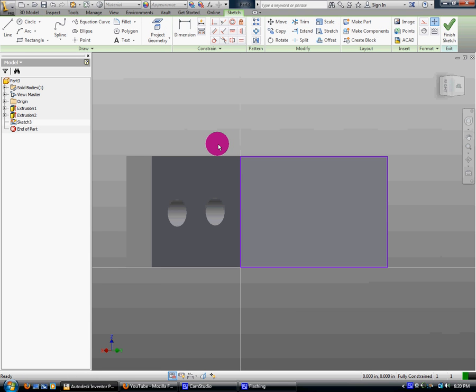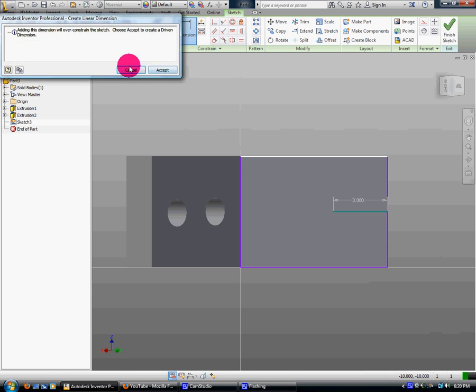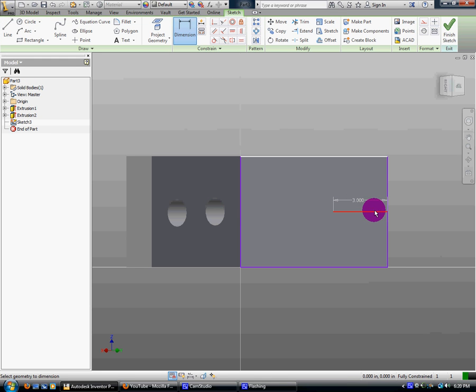And this time, I want to find my center hole, if I remember correctly. Yep. So it's going to be 3, 3, and 2. So I'm going to draw a line from the center here and over, and measure it. It needs to be 3, and if it's been done correctly, from here, cancel. That'll be 3, okay? And it is good. You could also just simply put a point there, and you could draw off that, but just drawing it for now. Okay, and it has a size of a circle of 2.95. Again, you could just draw it and go back and change it. Either is acceptable, doesn't matter as long as you get it done.